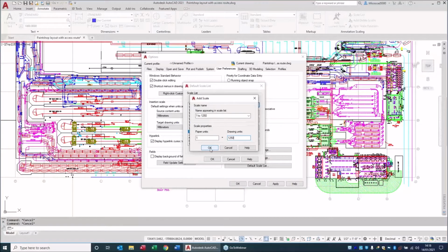Now if you're using AutoCAD Civil or AutoCAD Map, it'll handle all that with your viewports and viewport scaling quite nicely. The trouble with standard AutoCAD is that it's really designed and hinges around millimeters. But you can go in here and create, if you like, a millimeter scale list and a meter scale list by setting the drawing units to a 1,000 difference in there.